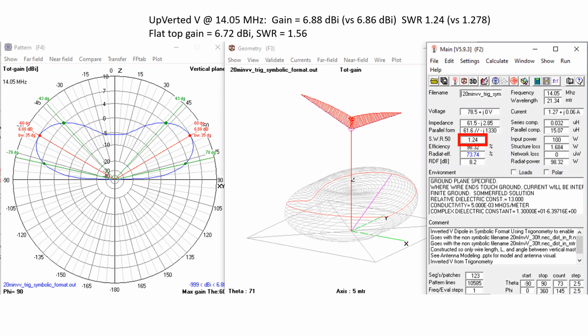The other comment, and I wonder what you think about it, is I've played with using 75 ohm coax for feeding antennas. 75 ohm coax is cheap, readily available and cheap. You have to be careful whether you get it with sufficient braid coverage. But anyways, dipole is basically a 72, 75 ohm antenna.